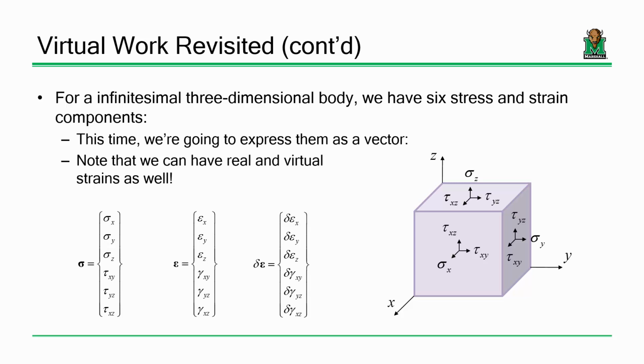One other thing I'll also point out, you all, I know, have done analysis using a little thing called Mohr Circle, right? I know you've heard of it, and I know you've done stuff with it before. Mohr Circle is a wonderful technique if all you're dealing with is two-dimensional stresses. It's not what we're dealing with in here. Ultimately, when we do complex 3D FEA, three-dimensional finite element analysis using real applicable software, you're going to get stresses and strains in 3 dimensions.